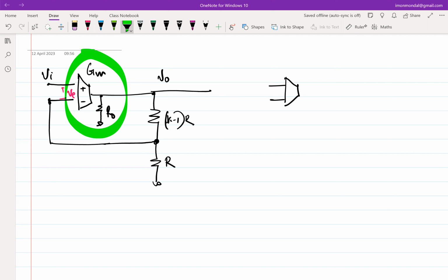So we said that using negative feedback, probably we can get a steady gain, but the cost that we pay is we are not getting those very high values of gain that we can get from an open loop amplifier. By open loop amplifier, what I mean is, if we have this, let's say this is my GM. If I simply find out the input-output relation between this contraption, that is V0 over VE, it will be GM times R0, which in principle can be a large value.